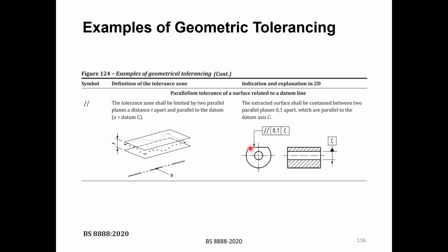So what we do here is say, okay, this center line defines datum C. And then at the top surface, we plot two surfaces, one at the top, one at the bottom, and the distance between them is t. The dotted line shows the flatness of this surface, and it could have any shape as long as it is within these two parallel theoretical planes. It should be accepted.